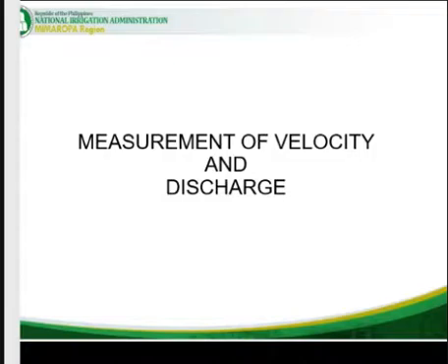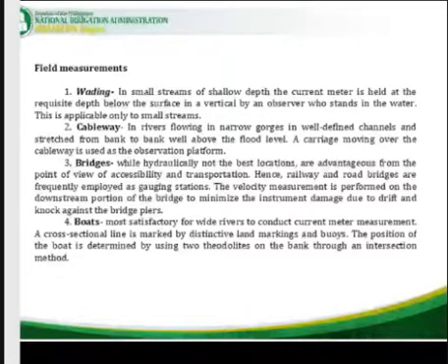Okay. So going back, in the conduct of field measurement, one is you do it by wading. Second, you can use cableway for big rivers. Then on top of bridges. And then if not, you use boats to measure the flow.